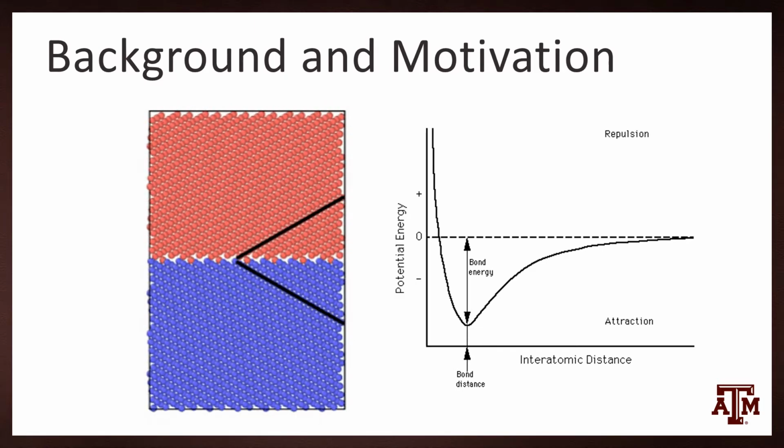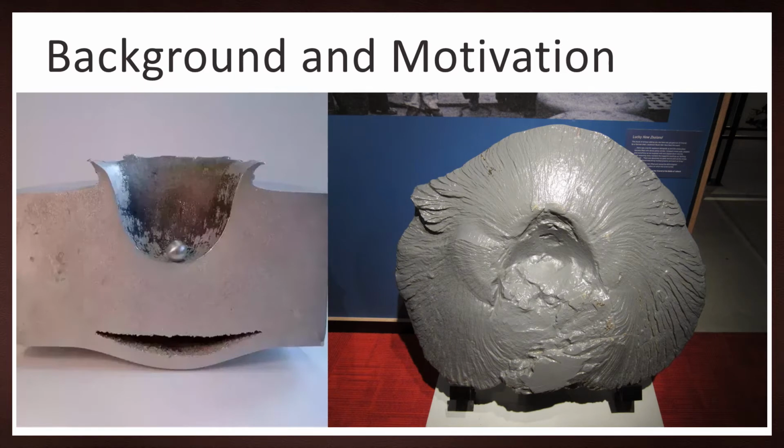like spall behavior. Spall strength is critical in materials used in armor and other high strain rate applications. Understanding its dependence on grain boundary properties, like misorientation, is important for designing materials with tailored shock responses. Spall behavior is dominated by cavitation, the nucleation, growth, and coalescence of voids in a material. I studied cavitation strength, which strongly correlates to spall strength.